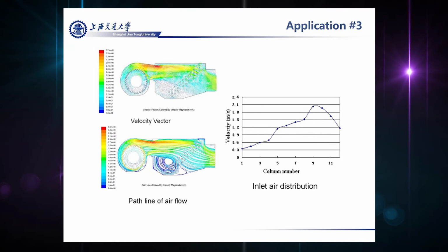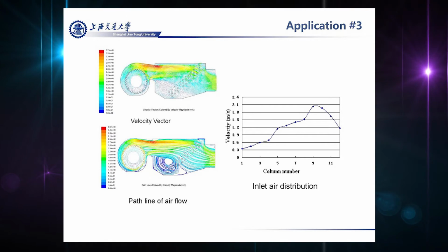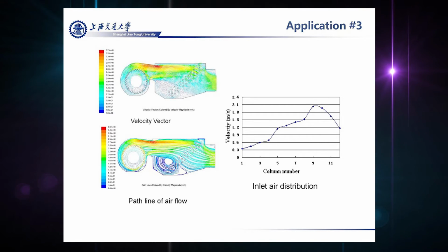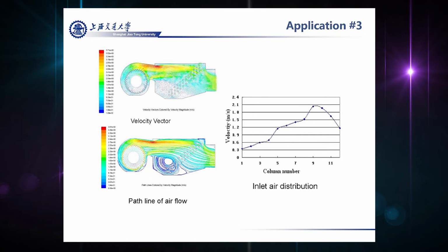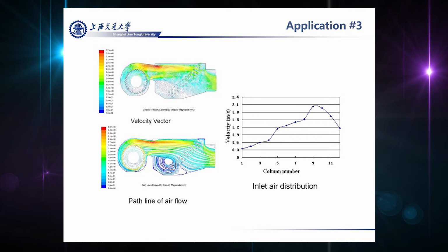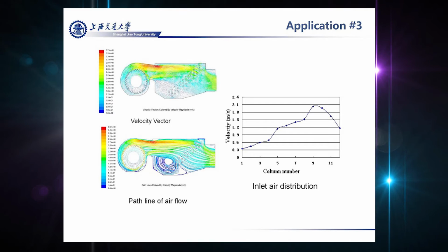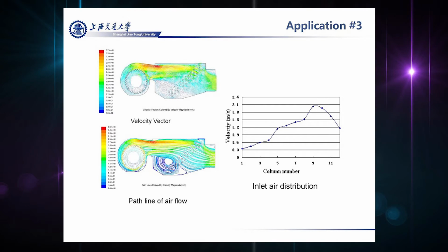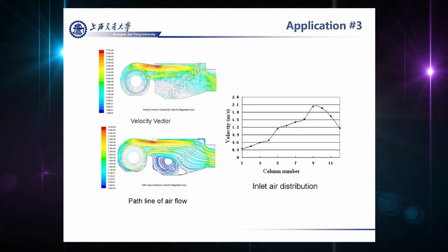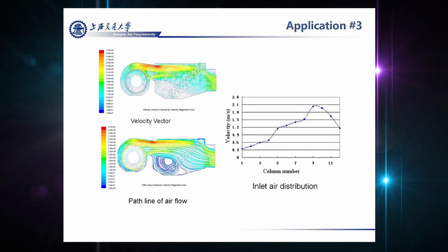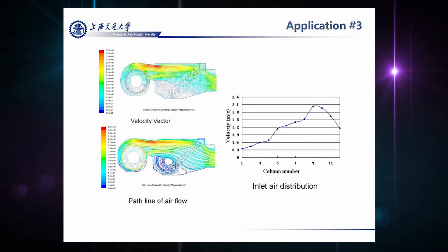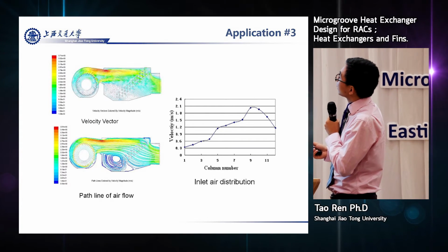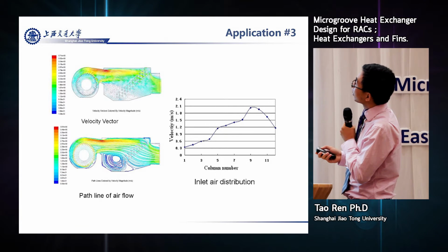This is the original 7 millimeter indoor unit with a 9 millimeter outdoor unit, and our new one is 5.5 millimeter. We get almost the same result, with a little bit lower efficiency, but acceptable because it's within the error range of the experiment. And we get almost the same capacity, a little bit larger, no big difference. This is a simulation result.